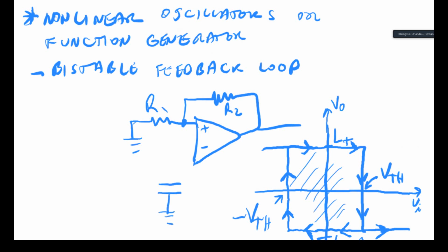So now this starts looking like your one shot a little bit, although this is different because this is an oscillator. The difference of the one shot is that it actually gets triggered with an event, and that's how you use the diode to actually trigger and discharge that capacitor based on an external event. Here we have no external event. This is an oscillator, but it's the same principle. It'll reset itself according to the timing set by this RC combination. So let's call this R and let's call that C.